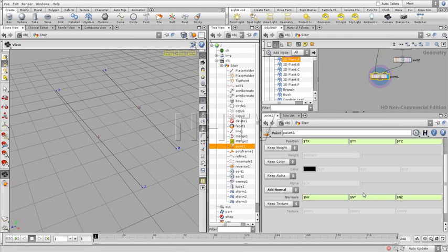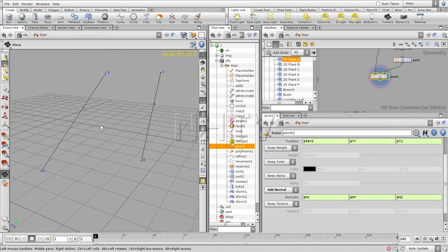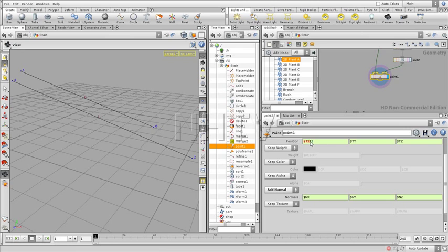Now I'm going to remove these variables over here. I don't need them. These are just saying that they're going to read in the normal values and place the normal values again. So in fact it's just not doing anything. It's the same with the position. It's taking in the position, so translate x for each point, translate y for each point, translate z for each point, and it's going to write exactly that value again. So if you would do, for example, times 2, as you can see, it multiplies those original values. Just leave it as it is again.